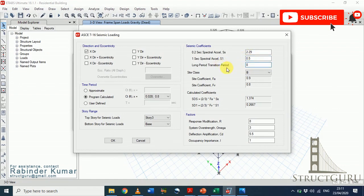Long period transition means, this value is used for high-rise buildings. If it is more than a 4 or 5 story building, you have to use it, whether you want to design a building for 10 seconds time periods or 11 seconds time periods. Basically this is an advanced topic. You must have some basic know-how about earthquake engineering. So just write 8 here, or you can also write 10 here. It's up to you. Now response modification factor.